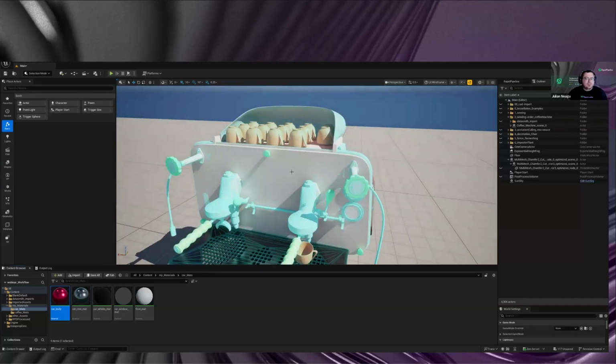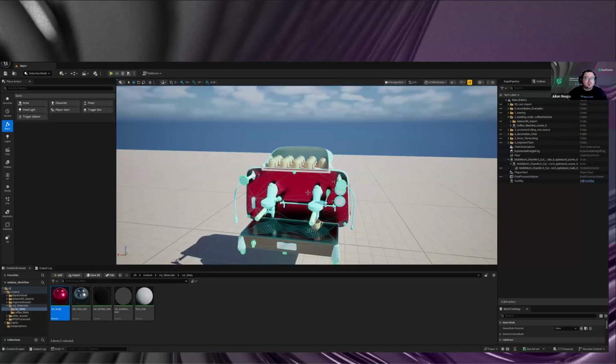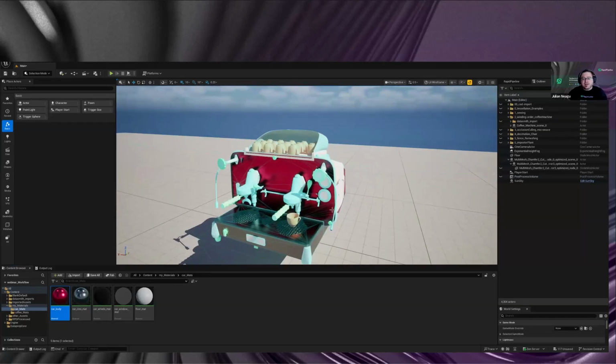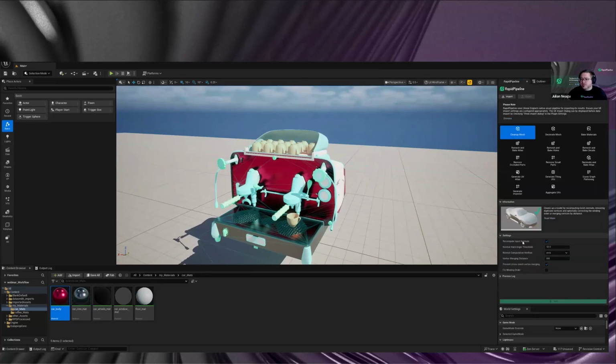There's something maybe wrong with the normals. Yeah, if there's actually a flipped normal here, I think that was the case here as well. We can always clean that up with the cleanup mesh operation as well, which will actually recompute the normals. And you can also have a normal angle. For CAD, we really recommend an angle of 30. That's basically the angle between soft shading and hard shading.